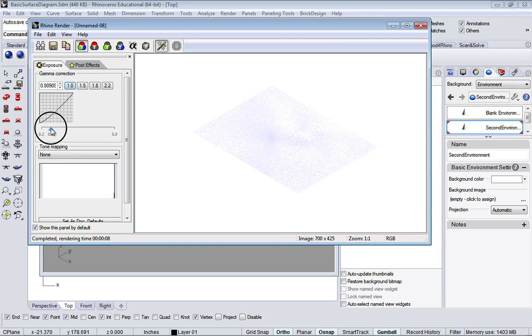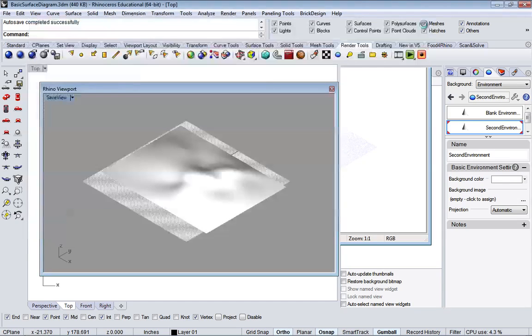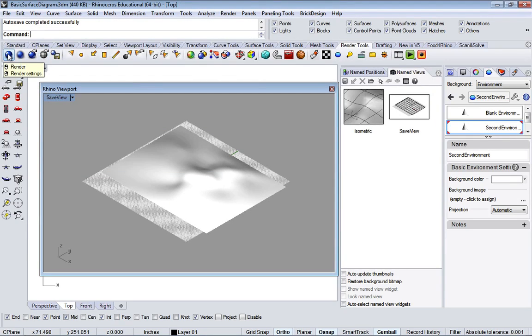And remember that what we want is an image that is maybe just a little darker than what we started with, because we can tone it down with opacity. But I'm just going to say that I want to get something real close. And that looks real close. And I want to make sure that the white background stays white, that we've got a hint of the topography, the light showing us shading on that topography. So that looks pretty good. So we know, okay, around 0.627, we'll just take a note of that. Okay, close that, and let's just render it for real this time.